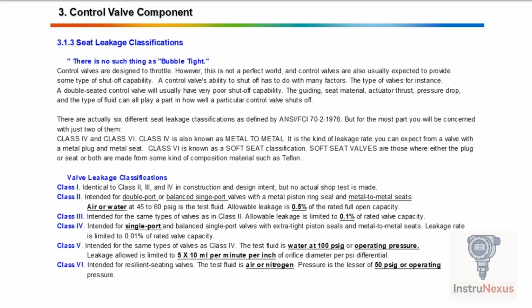In these valves, either the plug, the seat, or both are made of a composite material, like Teflon. These valves offer superior shutoff performance and are used when tight sealing is a priority. So remember, while perfect shutoff isn't guaranteed in control valves, understanding seat leakage classes helps you choose the right valve